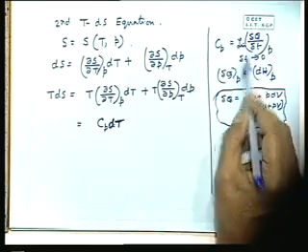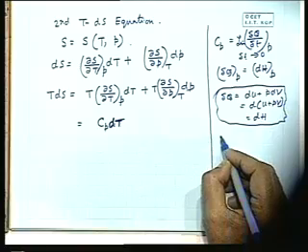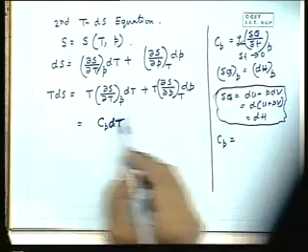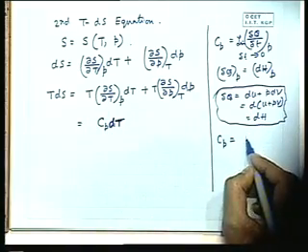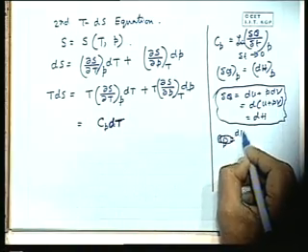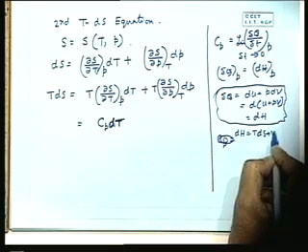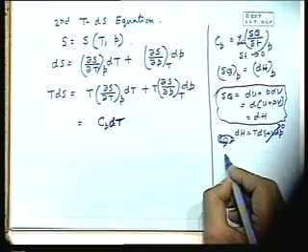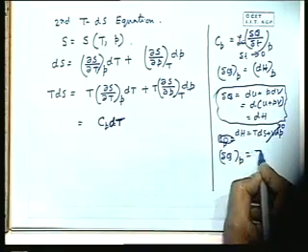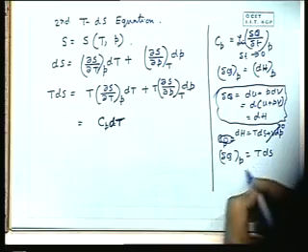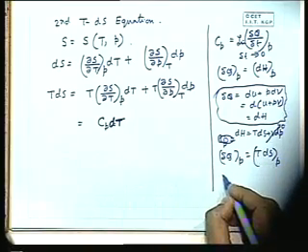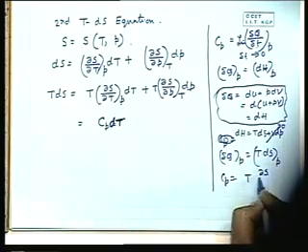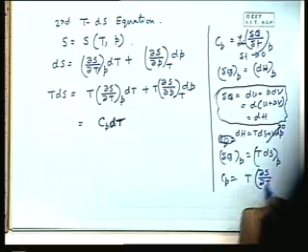Now if we define this, and write the expression for Cp, it will simply come as del H del T at constant pressure. So dH again, we can write dH is TdS plus VdP, from the property relation, because at constant pressure dP is 0, so dH is TdS. So del Qp is nothing but TdS at constant pressure, which means that Cp by this definition is del Q del T at constant pressure. We can write this in terms of the differentiation: T del S del T at constant pressure.